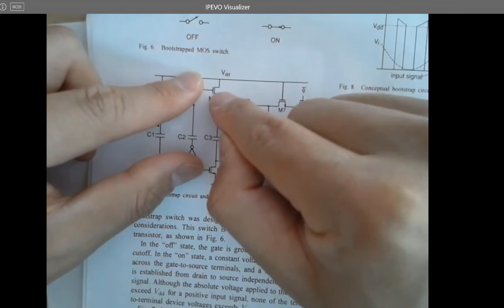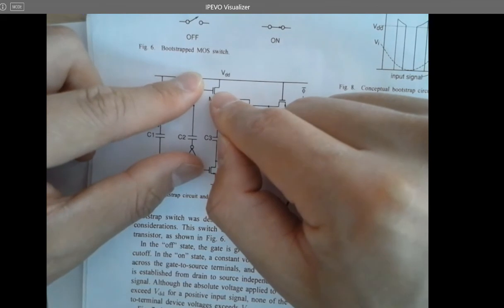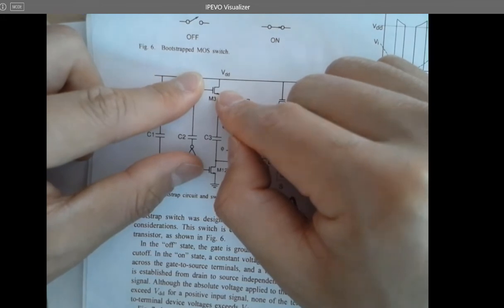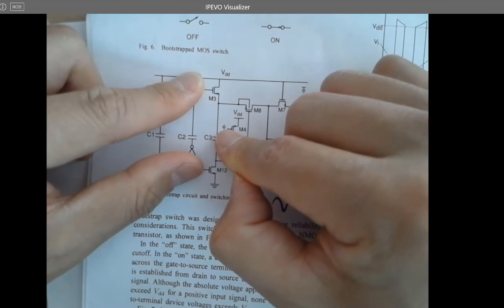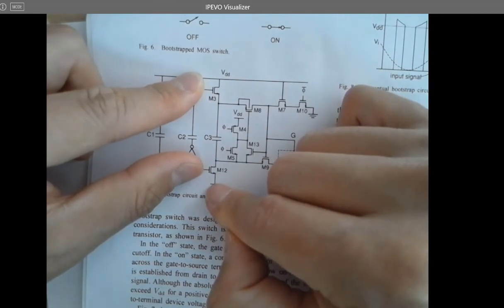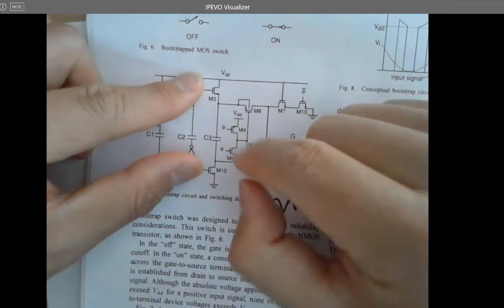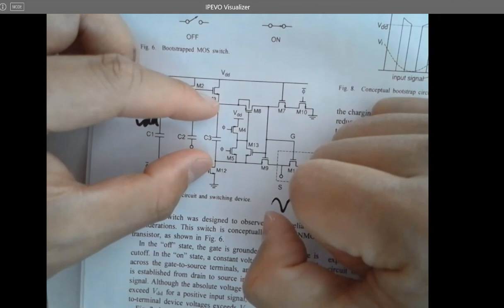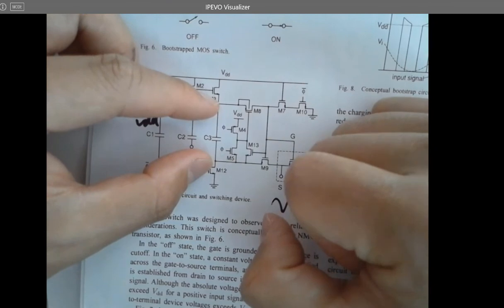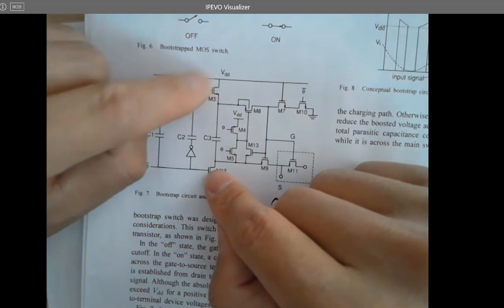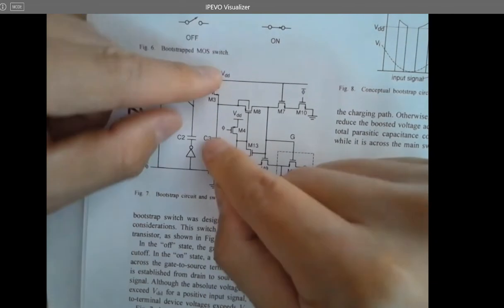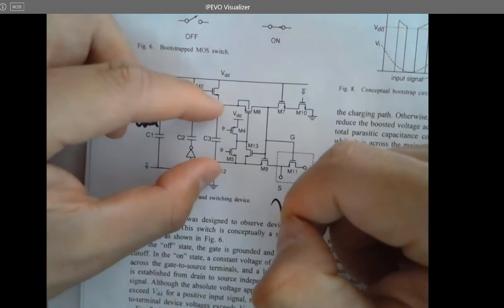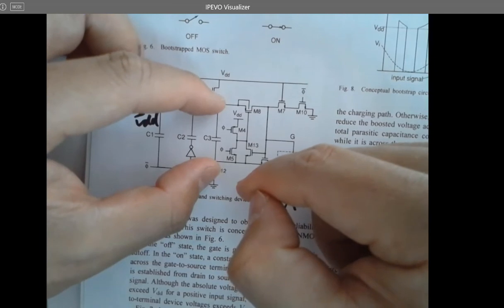Think about that, okay? I have a valve. Just imagine this is a valve. And I want to fully turn on this valve. Fully turn on. Keep in mind, I want to fully turn on this valve. If I want to fully turn on this valve, and I want to dump charges to the top plate of the capacitor, I want to pull the bottom plate down to ground as well at the same time. So I can source the positive charges from VDD, and I can pass the entire VDD to this point. So I can exactly have a voltage drop of VDD across this capacitor after I'm done with that cycle. Okay? So these two are being turned on at the same time. Turn it on, pull, boom, turn it off. Okay? Turn it on, charge, turn it off. So you are going to store charges to the two sides of the capacitor, and the voltage drop across this capacitor will be exactly what?